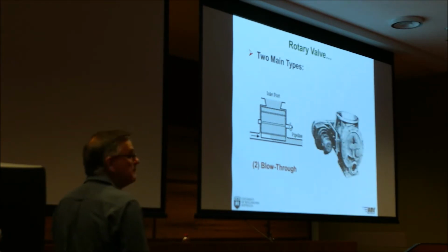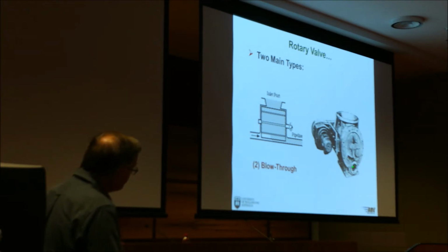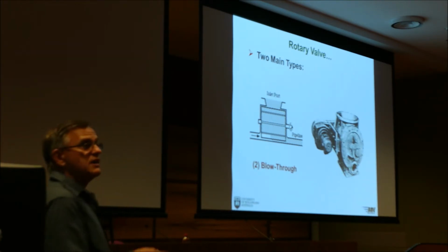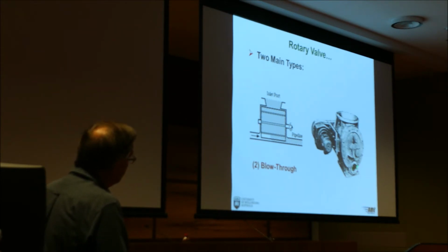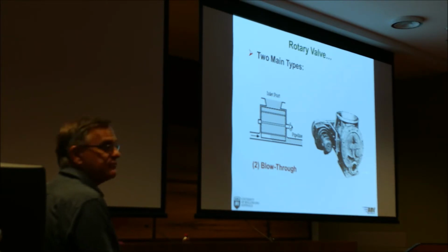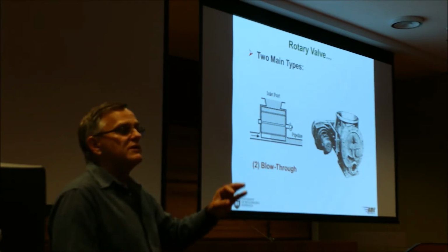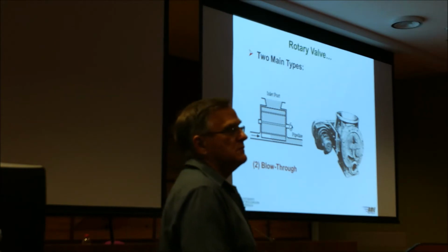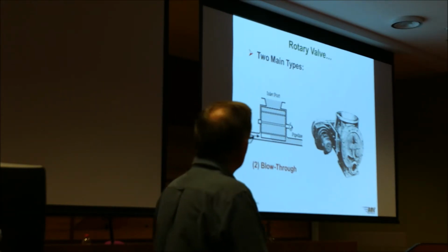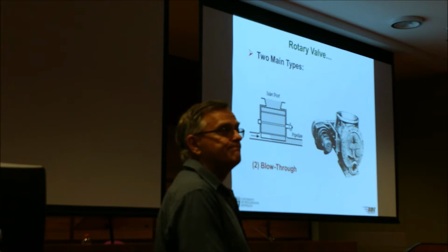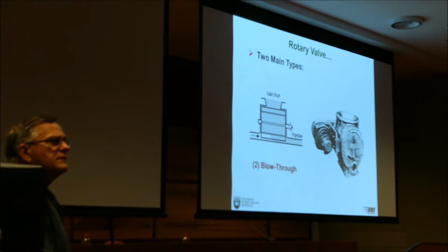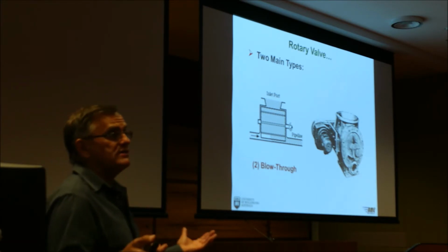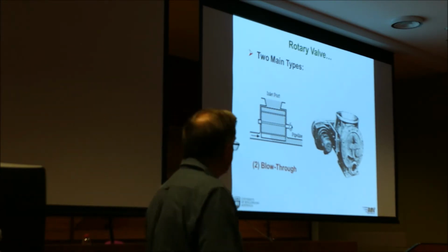Right there, so there's an example of a blow-through rotary valve. Again, with a round inlet port, you can also have square or rectangular, depends on the manufacturer. And here you can see where your pipe is connected, and your blades are exposed. So if your powder's abrasive, you've got to be careful. Otherwise, you can wear out your rotor very quickly. So I wouldn't use cement through such a rotary valve. Milk powder's not abrasive, so milk powder's good.